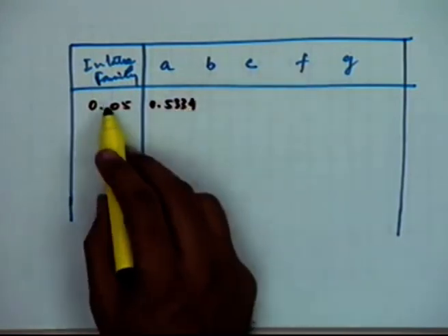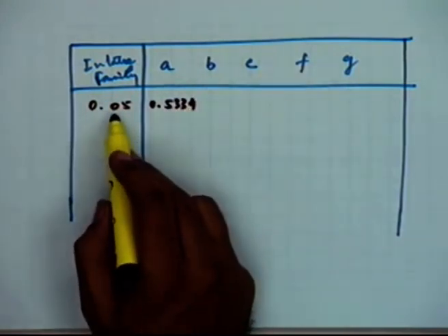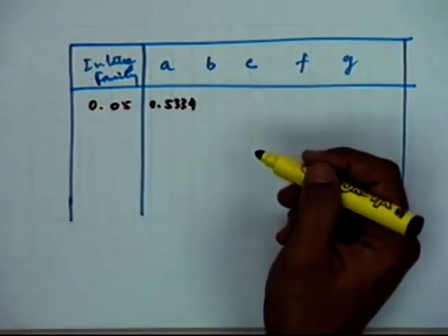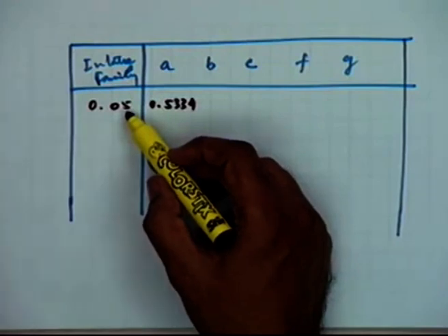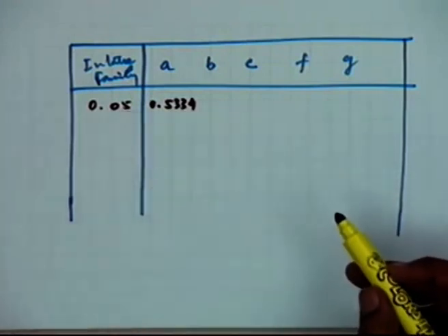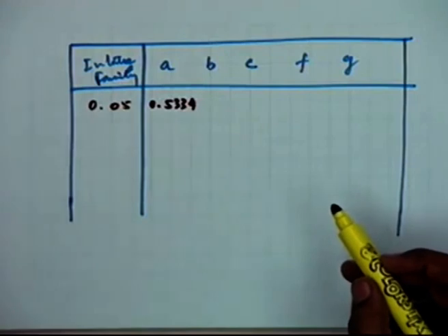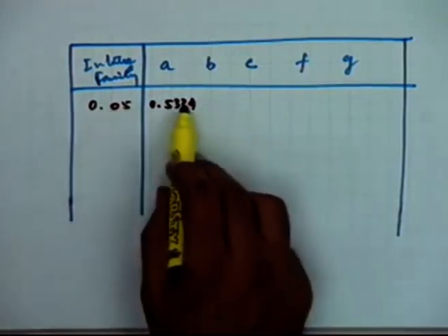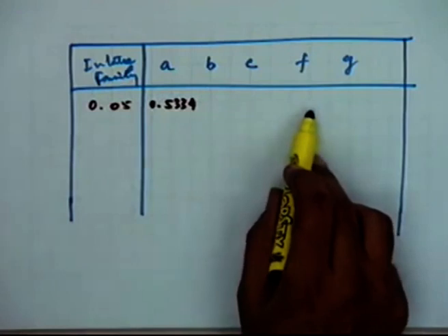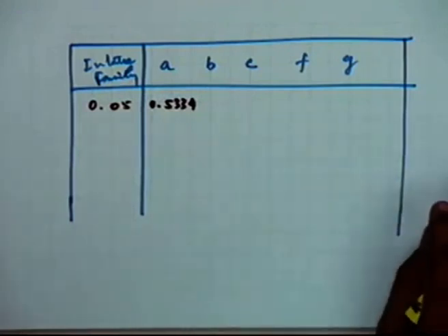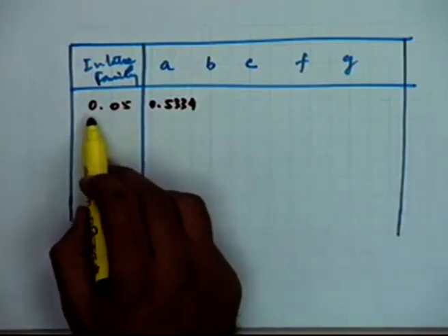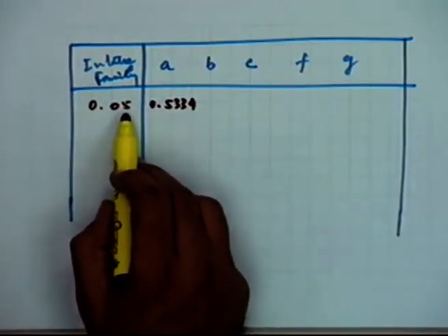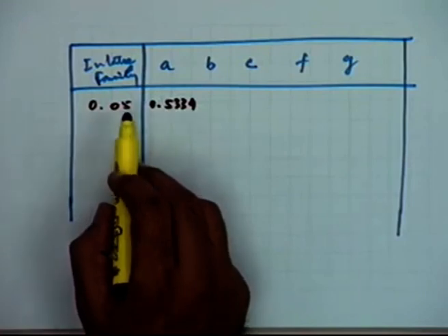This is the value of A when the intake family curve is 0.05, and this we had discussed earlier also, that the intake family curve of 0.05 means that this is the equation for which these parameters are applicable for a soil type whose basic infiltration rate stabilizes at 0.05 inches per hour. Is it inches per hour?